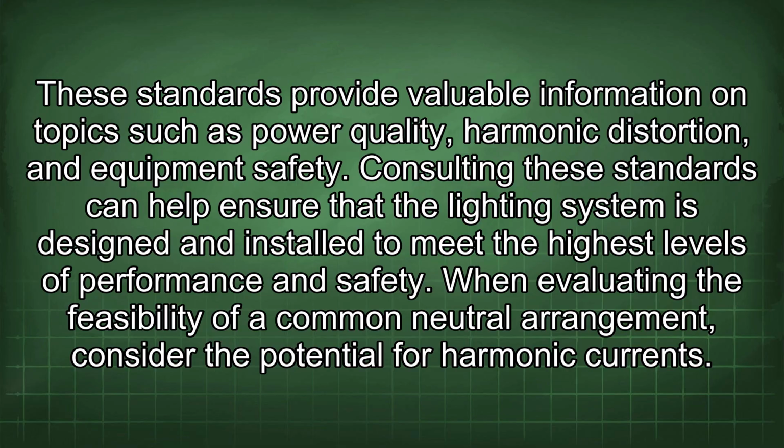Consulting these standards can help ensure that the lighting system is designed and installed to meet the highest levels of performance and safety. When evaluating the feasibility of a common neutral arrangement, consider the potential for harmonic currents.